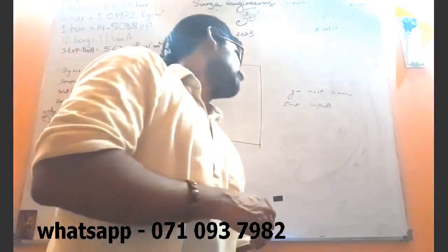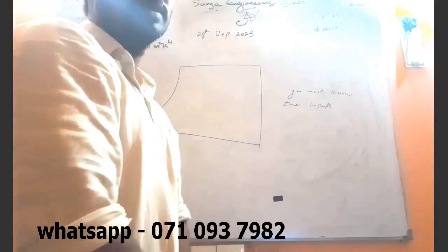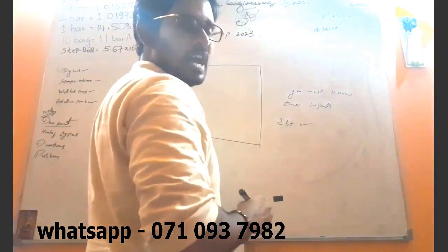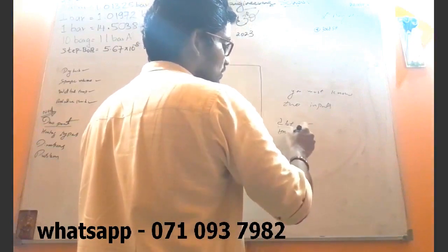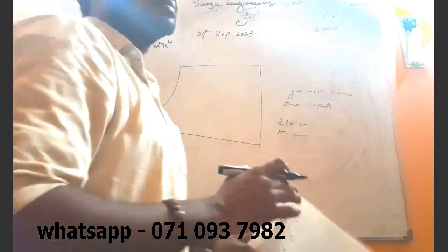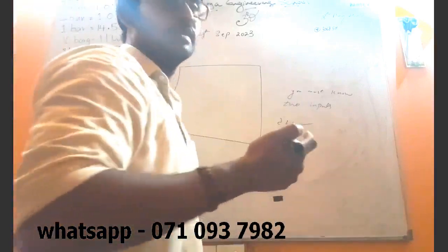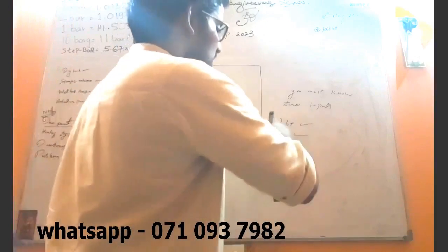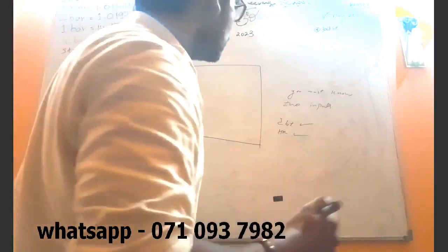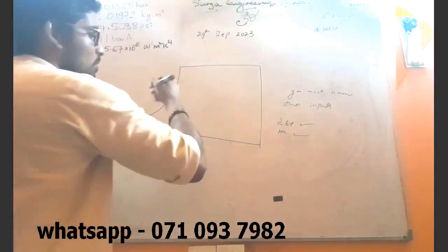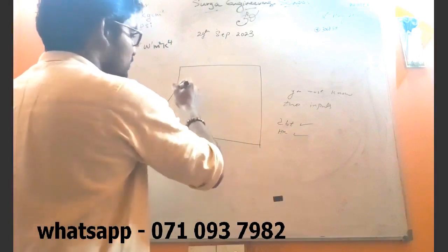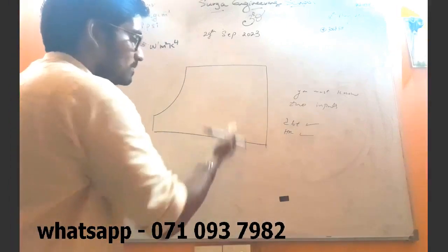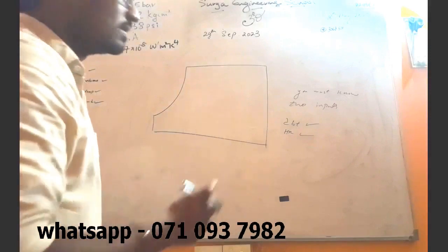Let's say for an example that we want to find the dew point. Let's say the dry bulb temperature is given, and the humidity ratio is also given. There are many ways; if another two parameters are given, it will be different. So just consider we are given two parameters: the dry bulb temperature and the humidity ratio. We know the humidity ratio goes along a horizontal line, and the dry bulb temperature goes along a vertical line, because those lines are vertical.